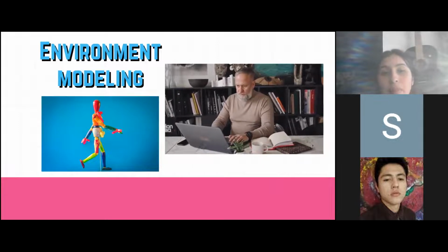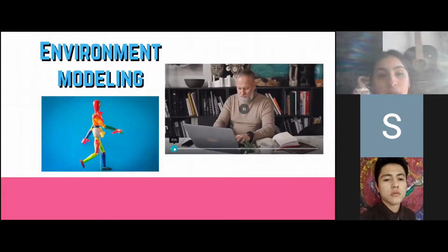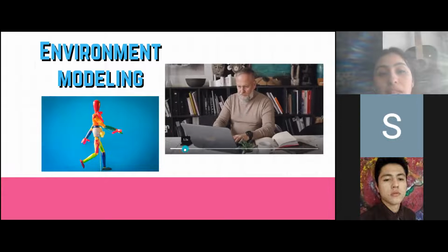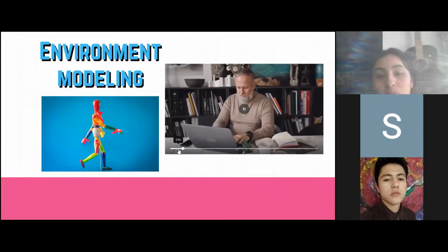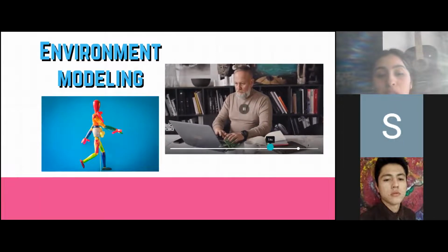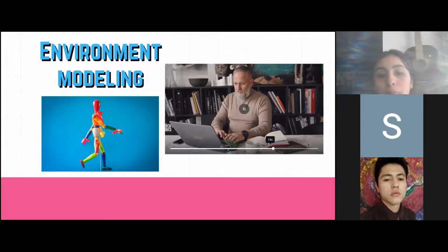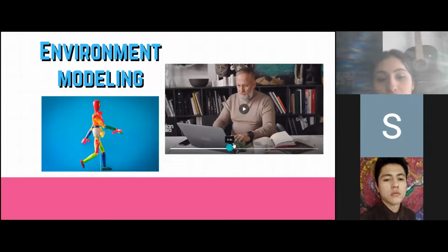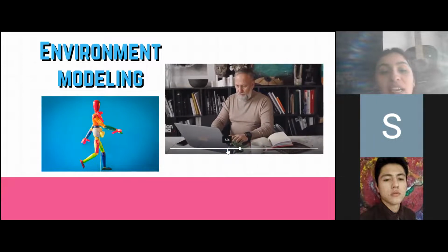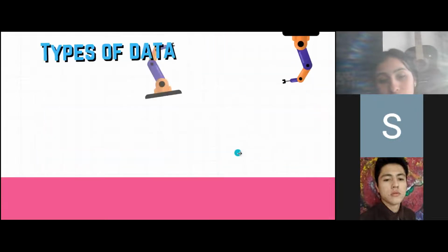Environment modeling. The environment model is the robot's representation of the objects with which it interacts. The models are limited to geometric characteristics such as position and orientation of the objects, and sometimes to their shape, dimensions, weight, etc. The models of the environment allow the robot to locate itself, plan paths, plan complex tasks, act autonomously and infer new knowledge.